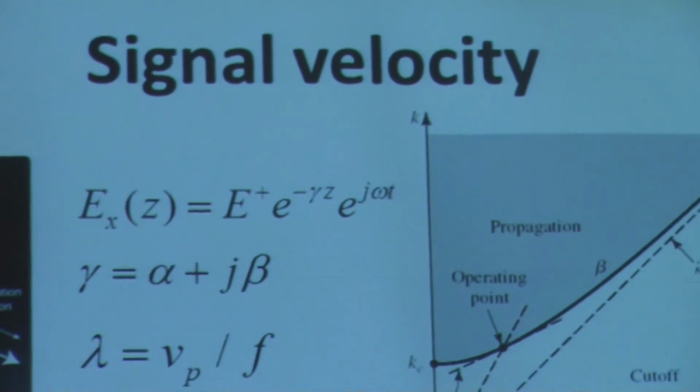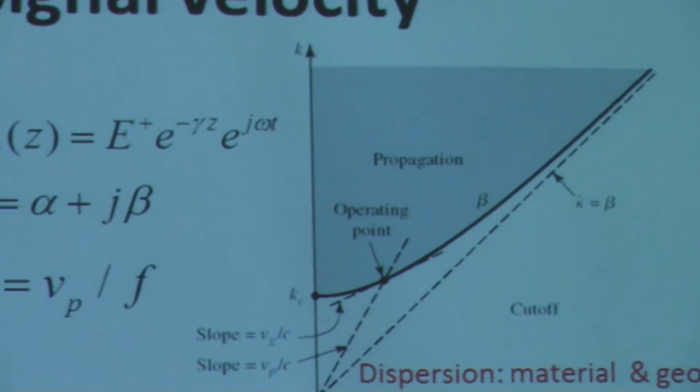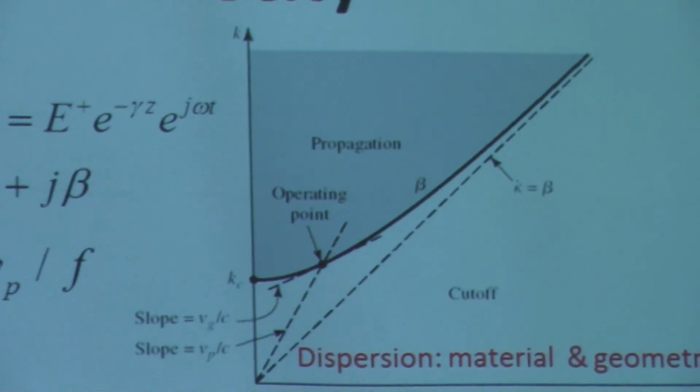And as I said, you can put metals on, let's say, your PCB board. You can put metals at different places to change the environment of your signal transmission line. Then you can change this omega-beta relationship. You can make it a very narrow band, so only signal in that frequency range can go through your transmission line. You can engineer this relationship.